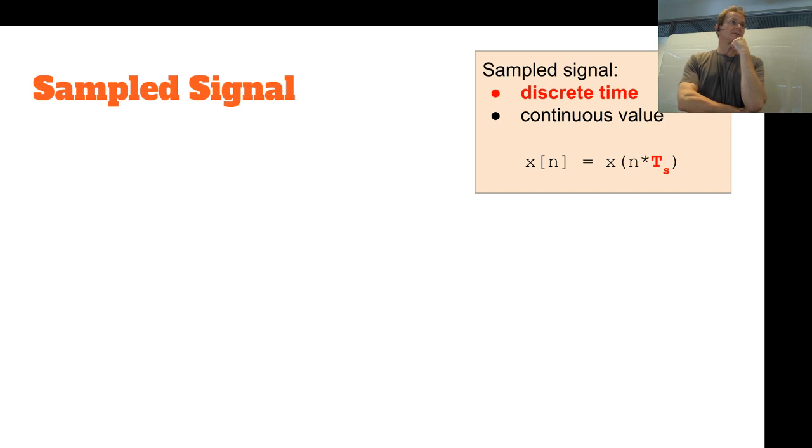This actually is the sampled signal analog, which is pretty much simpler, but also if you have floating point arithmetics, which you can always get by adding money to the design, then basically it's exactly the same as this sampled signal mathematics. I'm not adding the quantization of the value too early, only at the end, and just to see what is the effect compared to these continuous value signals.